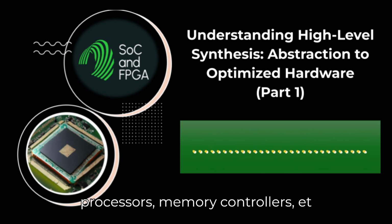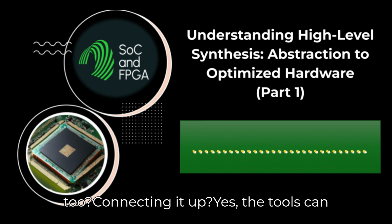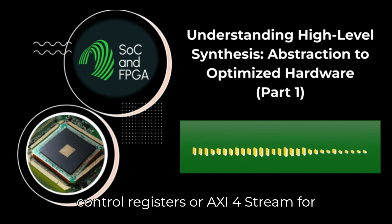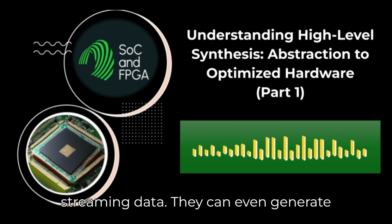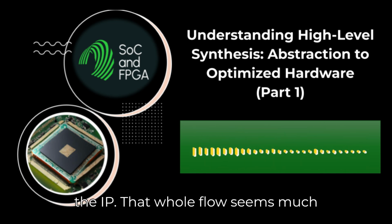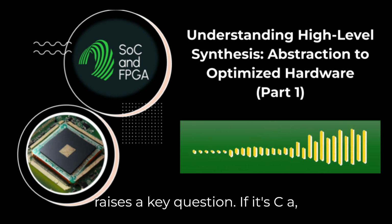processors, memory controllers, etc. Does HLS help with the interfaces too? Connecting it up. Yes. The tools can often automatically generate standard interface logic like AXI4 Lite for control registers or AXI4 Stream for streaming data. They can even generate basic software drivers to interact with the IP. That whole flow seems much faster than traditional RTL. But it raises a key question.